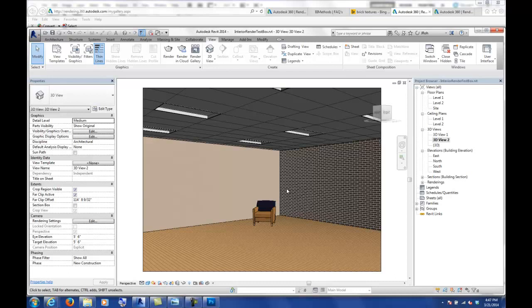paint icon, and then when this loads up, you need to select a material. So go ahead and select something, and then when it's selected, I scroll down to like wood floor. Don't hit done. Now select, and then when you're done selecting all the parts and pieces, you hit done. Yep. Paint and select item. Yeah. If you can't select your different components, that's probably why.